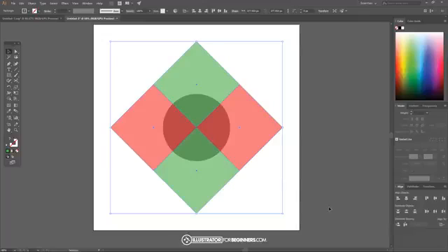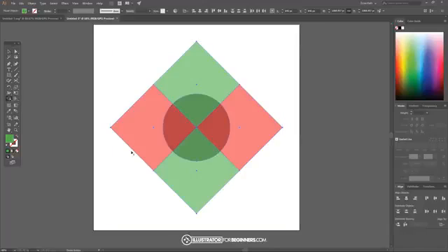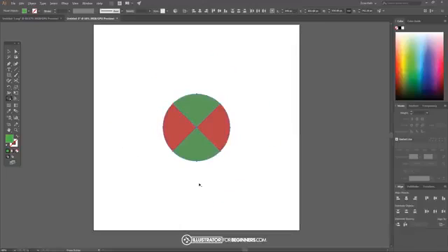And what I want to do now is click and drag over everything. And I want to go to the Shape Builder tool, which is over here. And I'm going to hold Alt on the keyboard and click on that piece right there, and that's going to delete it. And again, I'm going to hold Alt and click on these pieces all out here just to delete all of them. And what I'll do now is I'll go back to the Select tool.